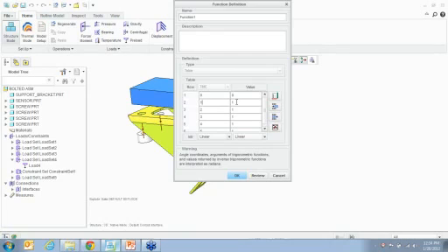At time 1, the value is 1. Now the value is not 1, it is multiplied by this factor. It's more of a factor. The load, if this value right here is 0.5 and the load is 1,000, then the value of the load is 500. So notice that function 1 starts at 1 second and is applied till about 5 seconds.